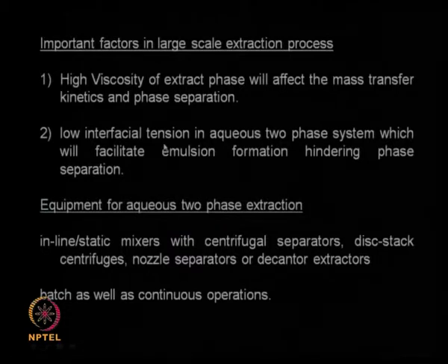If you are handling very highly viscous material, for example fermentation broth is going to be very highly viscous, because you are going to have dead cells, cell debris, intracellular material, DNA, so many components. So the viscosity is going to be highly non-Newtonian, and the values are also going to be very high. Now you are adding a solvent to extract a protein or a metabolite.